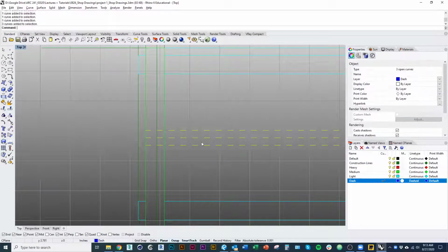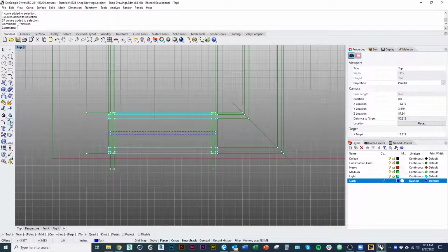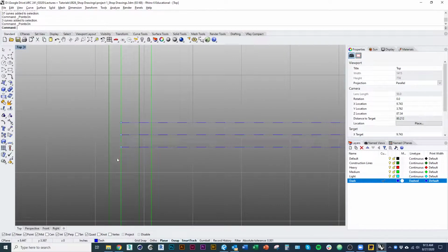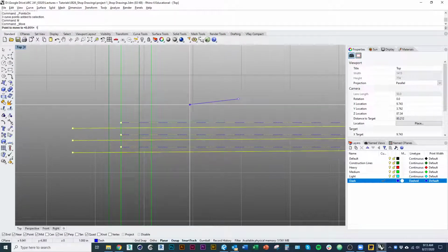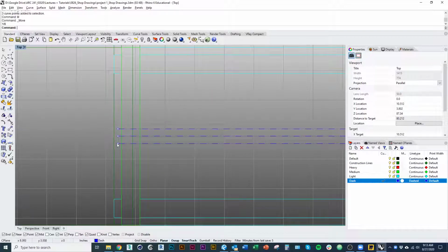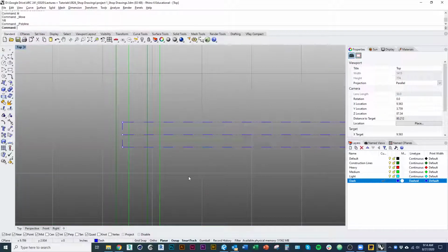But if you want to show points on for a bunch of things at once, you just select them all and you click that option. And I'm hitting escape, by the way, to get them to disappear again. Okay, so if we wanted to make these lines extend a little bit, we could select those endpoints, use the command move, and just click anywhere and move it by 1/8 of an inch, 1 divided by 8. I'm holding shift to snap to ortho, and I've just moved those endpoints 1/8 of an inch. So that's about where we would see the end of our handle in plan, right?